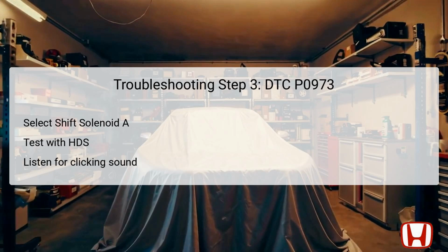If the clicking sound is heard, it suggests that the solenoid is likely operational, and you may proceed to the next step in the troubleshooting process. Conversely, if no sound is detected, it implies possible electrical issues up to that point. This step focuses on determining whether the solenoid itself or its supply circuit is at fault, and narrows down further actions necessary for effective diagnostics.